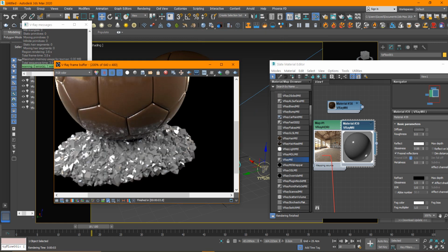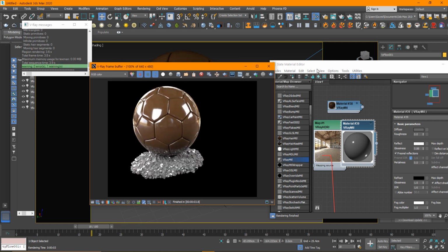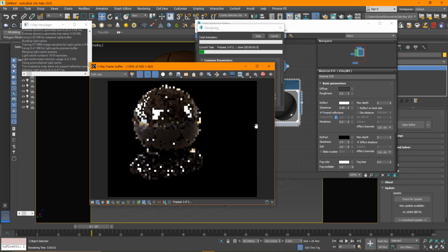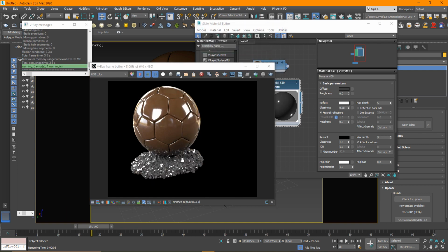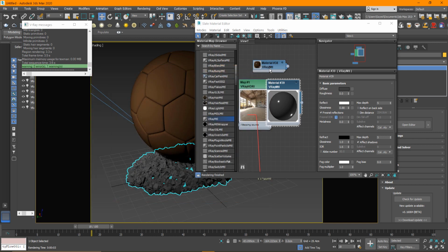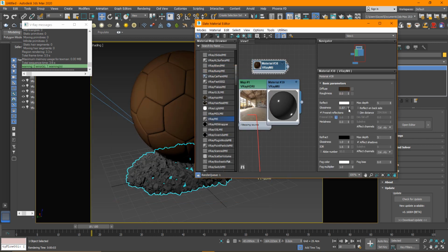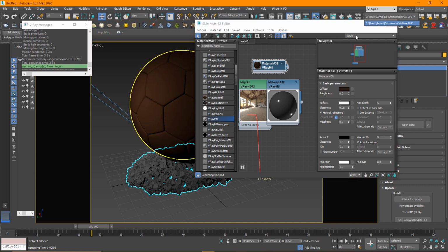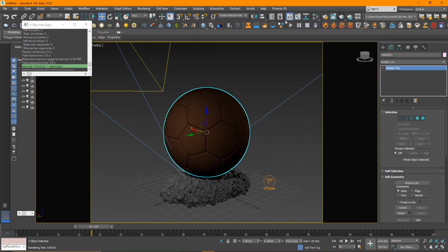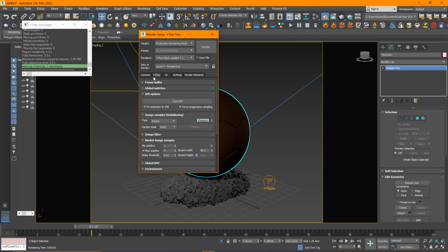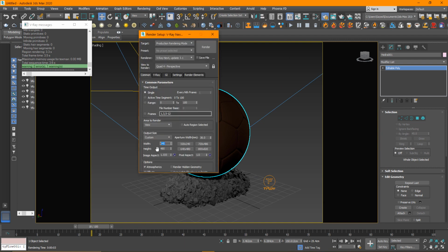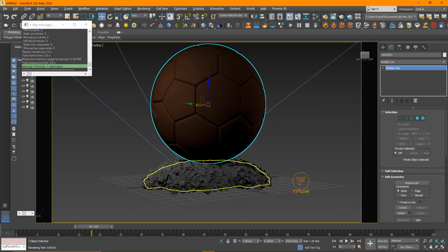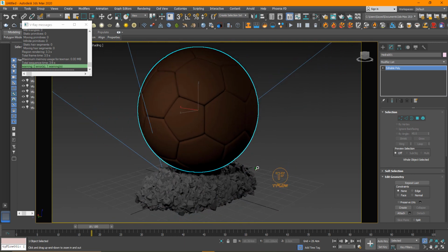It's looking not that bad. There are a couple of things that we can do to even enhance it. So I'm just going to make it even darker so that we get more reflection. Yeah, and let's get a proper render of this. So I'm going to adjust the gold material a little bit more, maybe make it even darker. And I'll just hit Z on this, change the render settings to maybe full HD, 1920 by 1080, and get a proper render of this, maybe from this angle, and then I'll zoom in a little bit, and then I'll increase the render settings.